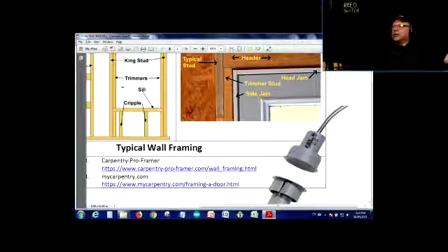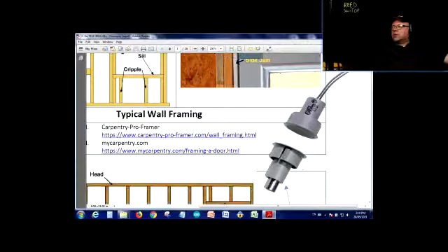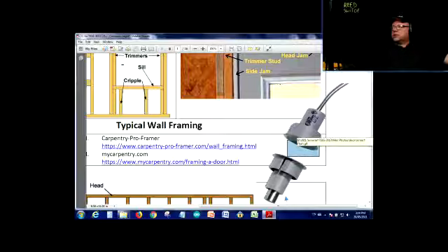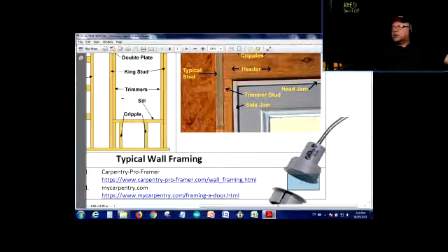And of course, on the other side of the frame, on the door itself, the door moves, so you're going to install a magnet. So when you close the door, the magnet comes in close proximity with the switch, and once it's close enough, the switch closes. So the switch is normally, well, it depends which way you look at it. When the system idles, it should be normally closed, but when you take the magnet away, the switch is going to be normally open. So you're going to have to pick a reference, which one you're going to consider normally open or normally closed. But you get the idea.